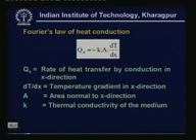As you can see, according to Fourier's law of heat conduction, heat transfer rate in x direction is equal to minus K A dT by dx, where dT by dx is the temperature gradient in x direction, and A is the area normal to x direction, and K is a property of the medium, and it is called thermal conductivity. And if you want to find out the heat transfer rate, obviously we need to know the temperature gradient.